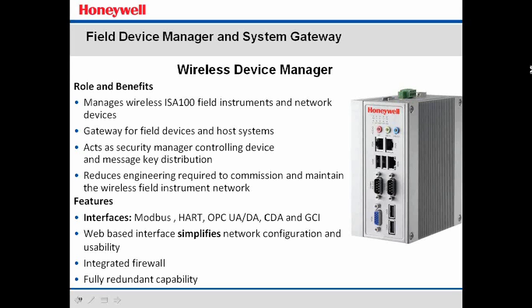Keep that in mind, please, when we're talking about distances. That is strictly line of sight. Any obstructions you have in between shortens that distance. So it becomes situational on how far a transmitter can get back to a field device access point. The operating temperatures are -40 to plus 75 Celsius. You probably don't have to worry about that too much in the U.S.